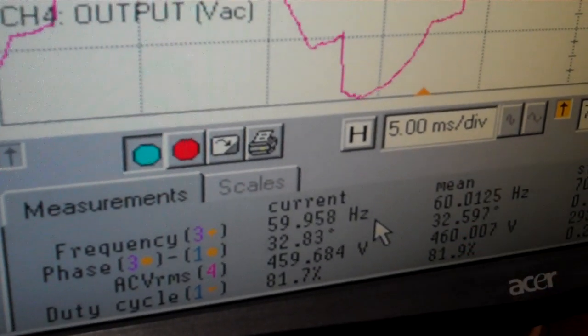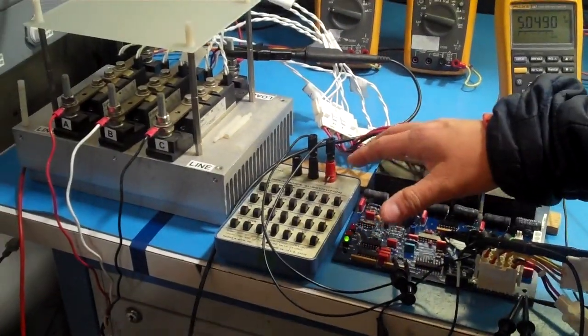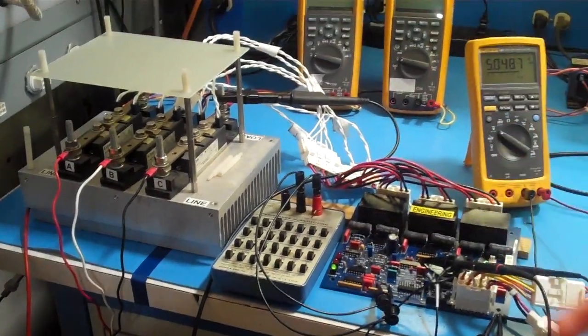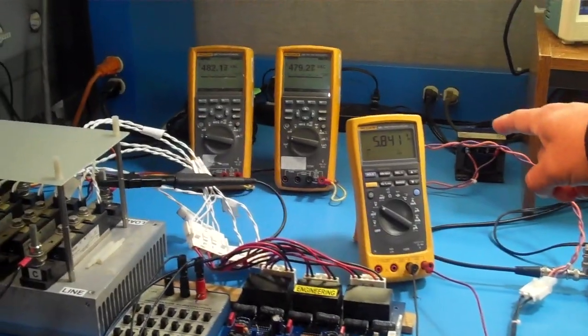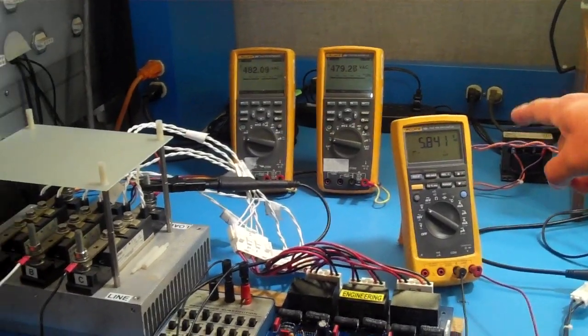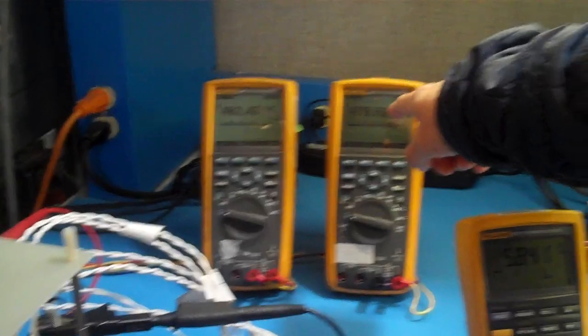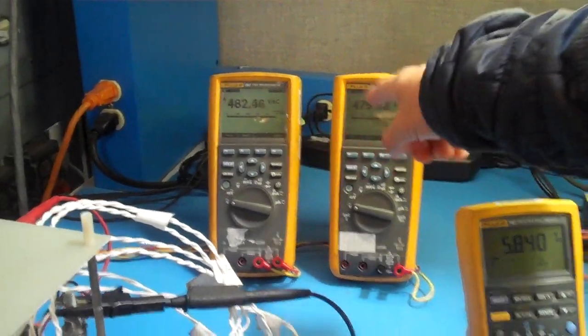32 degrees. Let's go ahead, keeping in mind that we have R24 equal to 249K. Therefore, we need to go to 5.85. So can we go to 5.85? There you go. That's good right there. 5.84 volts DC for SIG HI. Now we have 475, very close to 482.